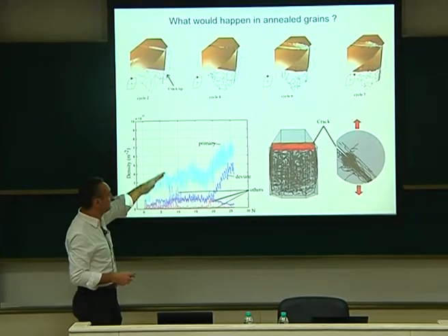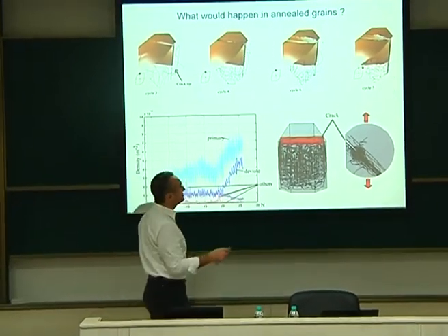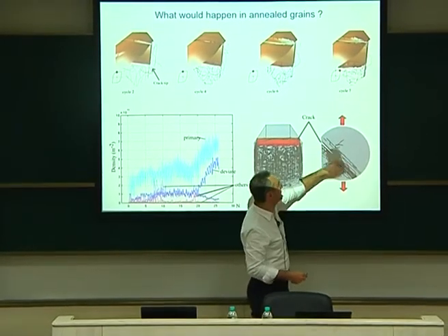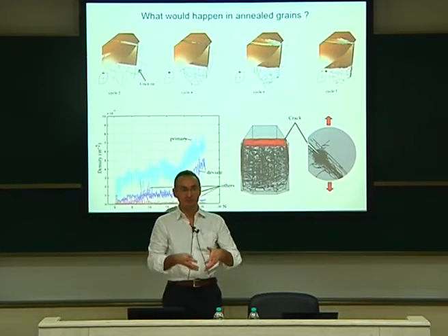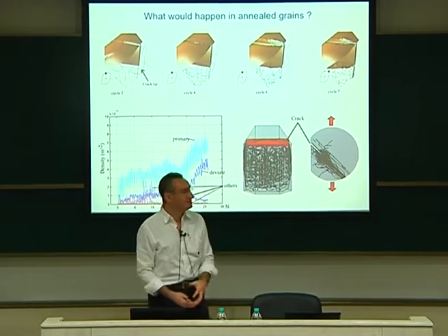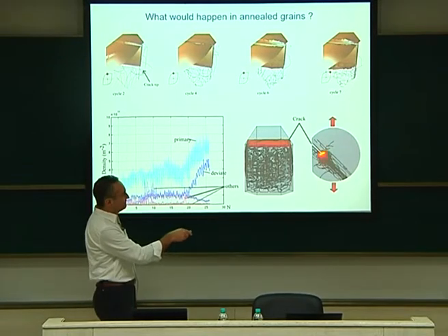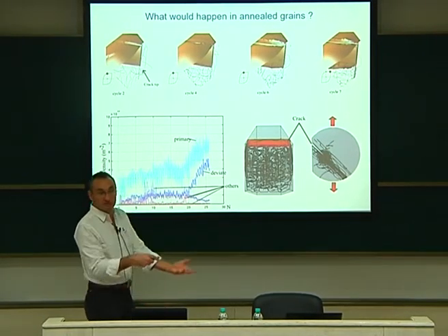We see that we don't have the same density evolution. And if you look at the dislocation microstructure, it's very much different. Now you have something which is totally located ahead of the crack. It's similar to what we saw yesterday with the MD simulation. Remember, in MD we saw this big dislocation spaghetti ahead of the tips. You have these big spaghettis which are developed ahead of the tip in this virgin material. So it's normal.